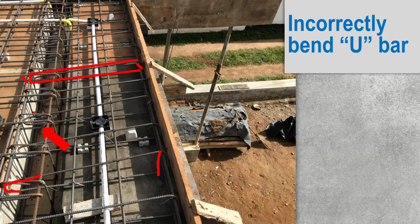Because of this incorrectly tied U-bar, they have got a shape like this. This is due to the incorrect height they considered when they bent the U-bar there. So the contractor has not placed this correctly, and this is not the correct way of doing it. You have to follow the correct norms, and maintain the bending radius at all these positions according to the particular guideline.